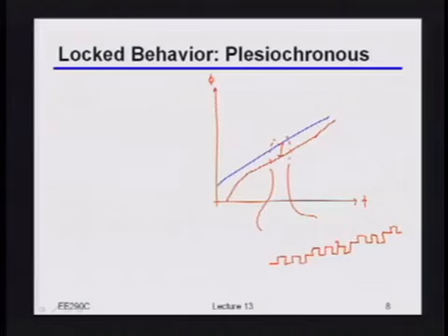There's actually another interesting implication of this. We said before that we want to make those step sizes really small, right? But what's the zero-order constraint that you have to satisfy if you're going to make this thing actually work? And there's some reasonable ppm offset between them. That it can catch up as fast as the ramp. Yeah, exactly. So here you have to make sure that your step size is big enough to basically, as you said, quote-unquote, catch the ramp.